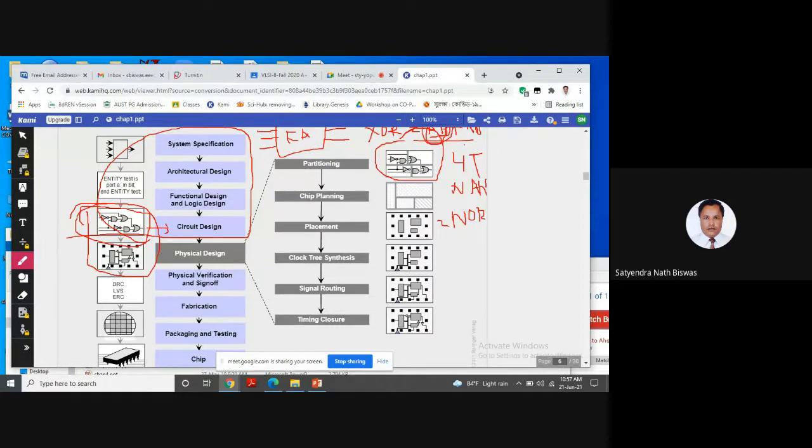But we can put the AND gate also with the inverter and make it an inverter and an AND gate in the bottom left here, right? We could do this part as one part, and put only the OR gate in the bottom right, but we don't know why we made it this way. So we have to find that, and that is called partitioning.